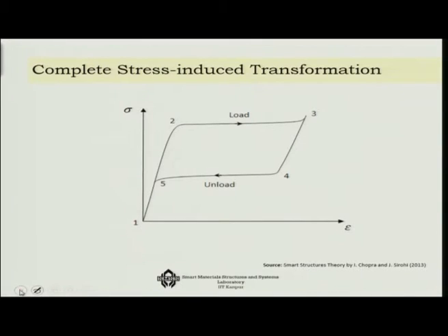If I look at the pseudoelastic behavior, that means here I am at austenite phase, and then I am increasing the load, okay, up to point 2, the elastic loading is over, suddenly the phase transformation happens.